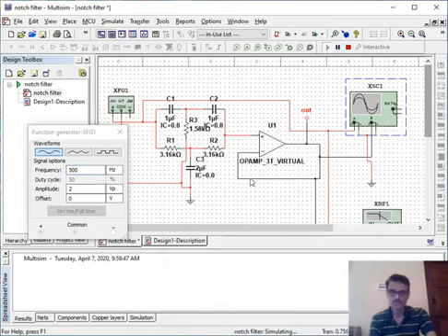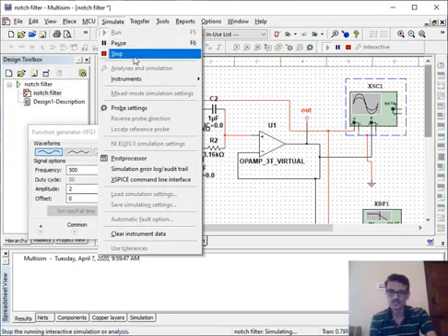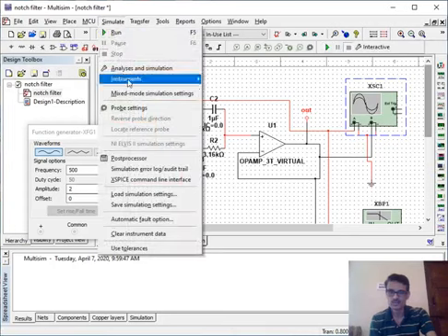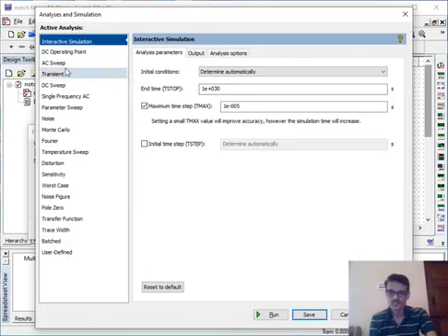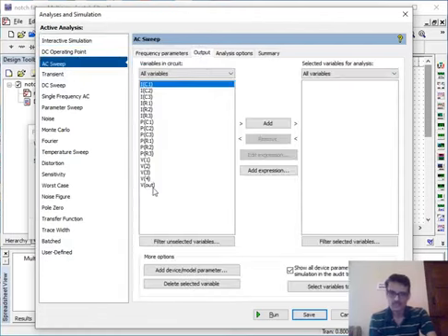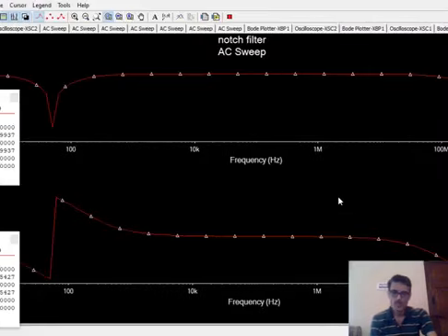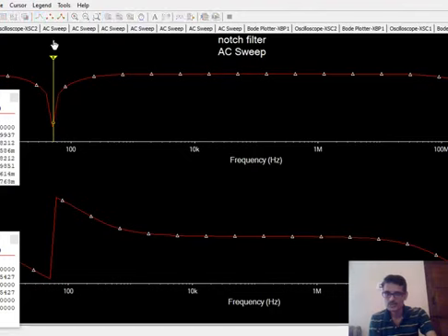Now you can observe even the AC analysis of this. So let me stop the simulation and set the analysis for AC sweep. This is fine, I believe. I think we can check this output, give this. Done. Now yes, you can see over here, this is the response I am getting, the frequency analysis.